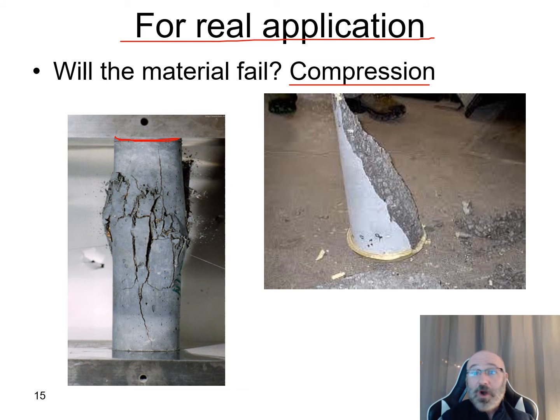And then as more of the water comes down in there, it fills it up and then it freezes and expands. So then you get that freeze thaw expansion within that small crack from the corrosion on the rebar, and it gets worse and worse and propagates more and more. The rebar gets more corroded, the cracks get bigger, and then that turns into a delamination at that level, and then that propagates up to the surface, and then we start seeing those potholes.